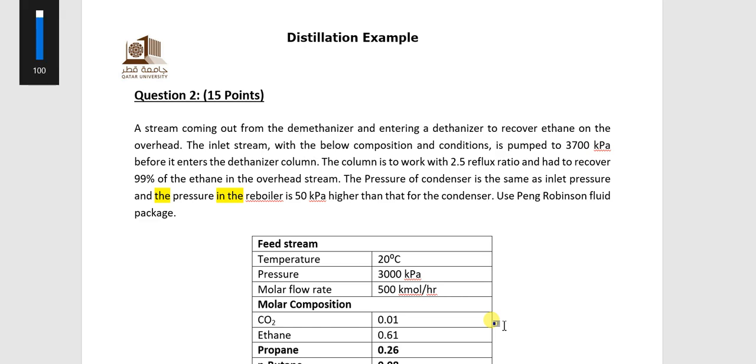I'm going to simulate this distillation example using HYSYS. You can see the problem statement: a stream coming out from a depropanizer and entering a de-ethanizer. De-ethanizer means we are going to remove ethane, to recover ethane on the overhead.